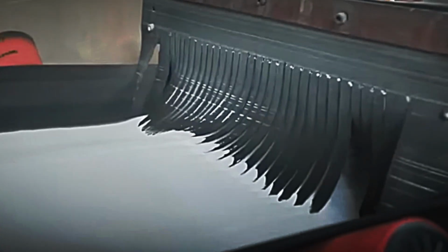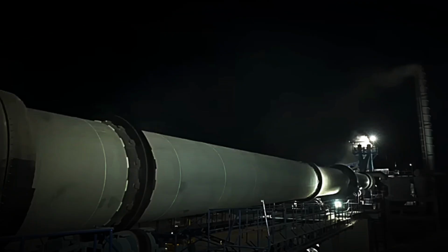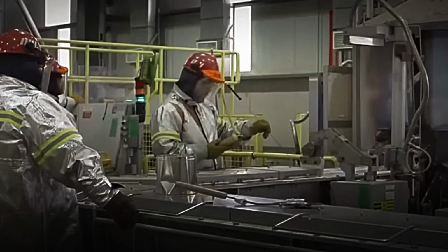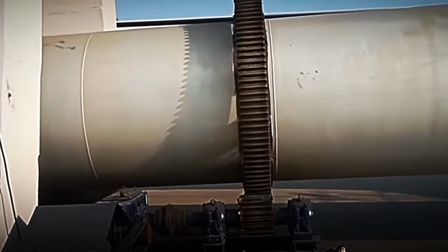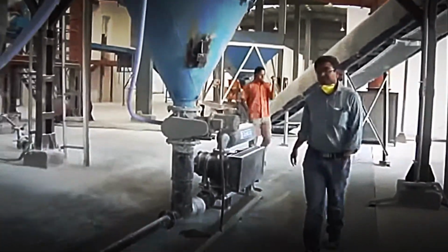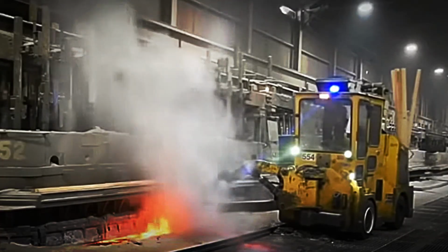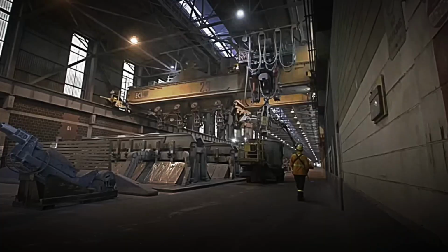Here, crushed bauxite is mixed with caustic soda, sodium hydroxide, in a huge reactor called a digester. The caustic soda dissolves the aluminum compounds present in the bauxite, especially the aluminum hydroxide. To accelerate the reaction, the mixture is subjected to high temperatures, between 150 and 200 degrees Celsius, and pressure. The result is sodium aluminate, a soluble compound that will be the basis for obtaining the white alumina powder.